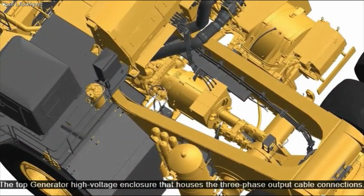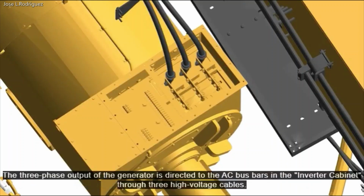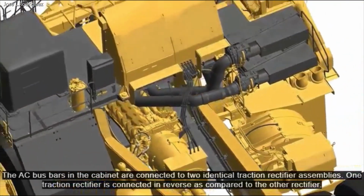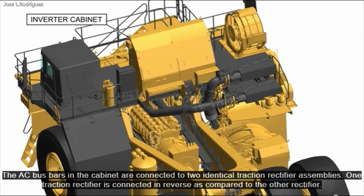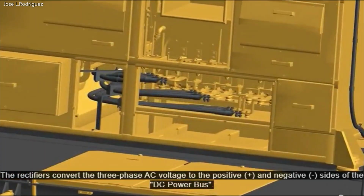The top generator high voltage enclosure houses the three-phase output cable connections. The three-phase output of the generator is directed to the AC bus bars in the inverter cabinet, through three high-voltage cables. The AC bus bars in the cabinet are connected to two identical traction rectifier assemblies. One traction rectifier is connected in reverse as compared to the other rectifier. The rectifiers convert the three-phase AC voltage to the positive and negative sides of the DC power bus.